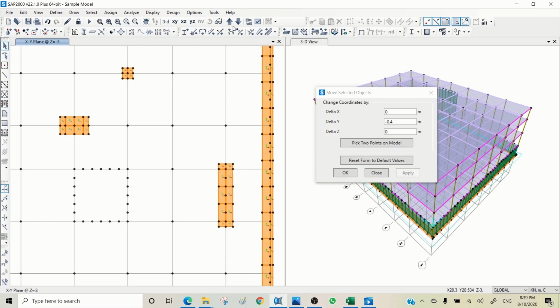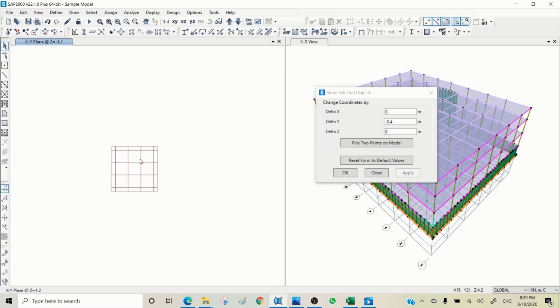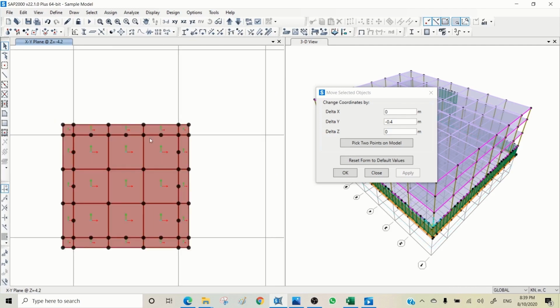piles here, and then for the lift, what we want to do, generally piles should be underneath the lift wall. So that means we need to enlarge the pile cap here. Here, if we have 600 pile, we need to have 300 millimeter extra extension. So I need to come to, let's use whatever we have currently here. Just so I'm choosing those joints and applying -0.3, and do the same for the other side.